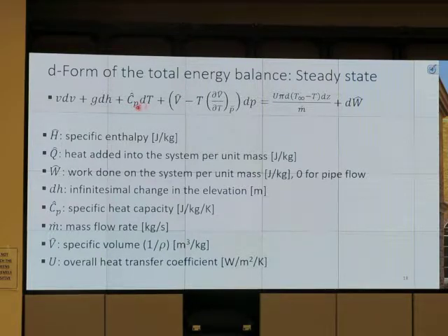So dT, when temperature increases, dT is positive. When I write it like this, it means heat is added to the system. And this term, T infinity minus T, means that the environment is hotter than the system, so heat is being added to the system. If you check, each term is positive. In the case where T infinity is less than T, we lose heat.